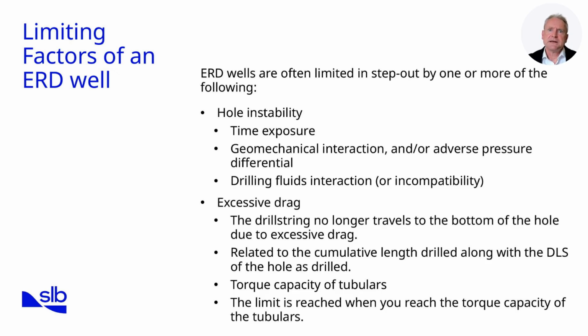Drag is another limiting factor. Over long distances, the drill string can experience so much friction that it fails to reach bottom. This is tied to cumulative hole length and the dogleg severity along the path. Finally, torque capacity of tubulars sets a hard limit. Once torque approaches the design threshold of drill pipe or connections, additional step-out becomes unsafe. Together, these factors determine the practical maximum reach of ERD wells. On the next slide, we'll see how this shrinking margin of error is represented graphically.